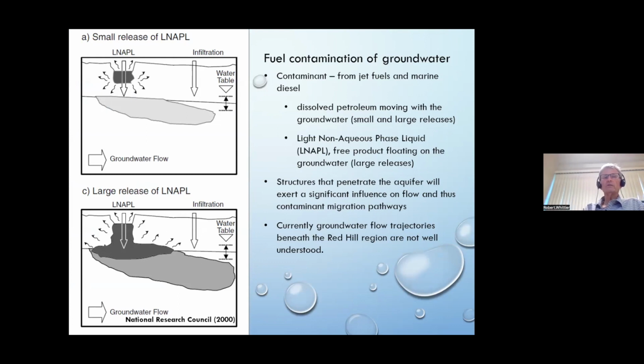So this diagram on the left actually shows our problem. We have a potential source of fuel contamination, and hydrocarbon fuel is light relative to groundwater and also immiscible, in that it doesn't mix with water, so it's referred to as a light non-aqueous phase liquid. In small releases, we can retain the LNAPL, or free product phase, within the vadose zone, but due to recharge, we'll get contaminant migration, the dissolved phase, to the water table.